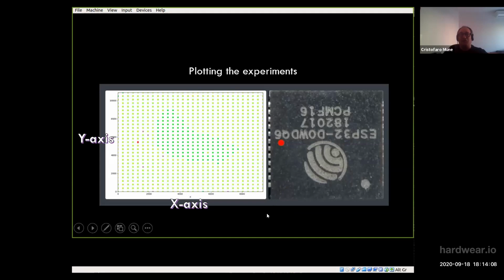This is greatly interesting, especially when you start mapping the behavior to a number of variables that are part of your choice space, or your injection space, the glitch parameter space. That's how we call it. And for sure, one is the physical location of the probe. So we start executing this code, and we start injecting during this code while scanning the surface.